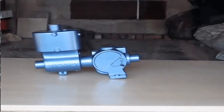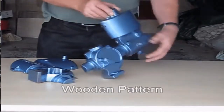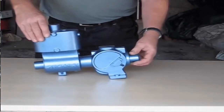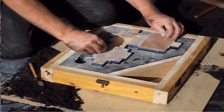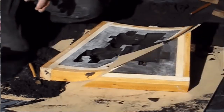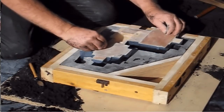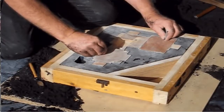To avoid that, we should have the shrinkage allowance. Usually, the pattern makers correct for the solidification shrinkage and thermal contraction by making the mold cavity oversized. The amount by which the mold is made larger relative to the final casting is called the pattern shrinkage allowance. Casting dimensions are expressed linearly, so the allowances are applied accordingly.